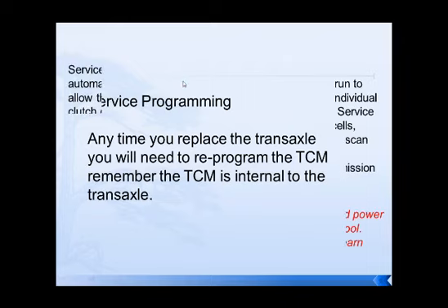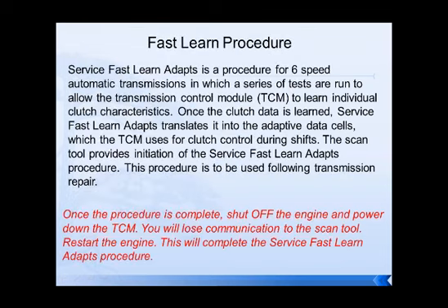Fast learn procedure. The fast learn procedure for this transmission is no different than the fast learn procedure for the other 6-speed GM transmissions. You're going to have to be able to clear the adapts and then relearn the adapts themselves.